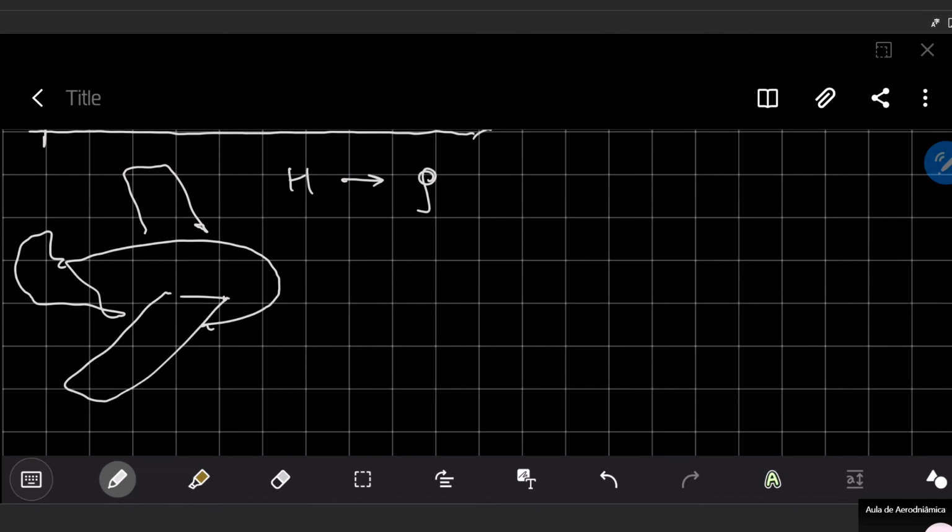On the ground level, we know the density is the standard density. On some altitude, the density is changing, density is decreasing. So to know the density, you just need to go to the end of the Anderson book and you will see standard atmosphere table from where you can find relation between your altitude of the flight and the density.